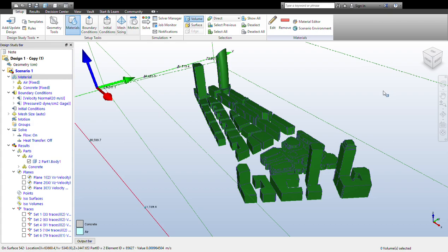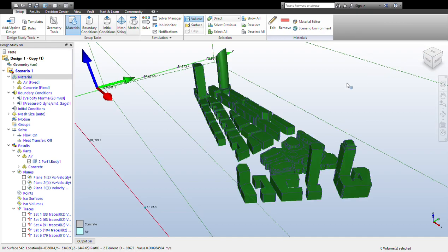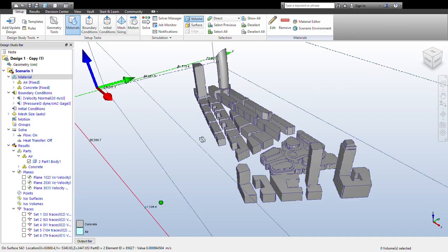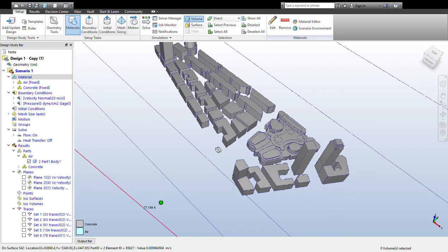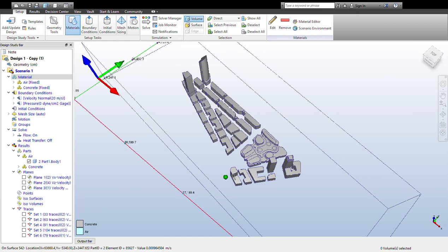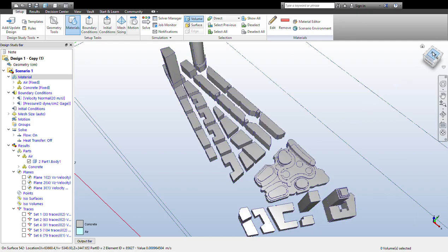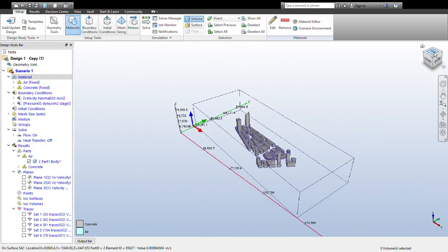What's important here in this demonstration is to show you the behavior of wind in areas such as Al-Abdali, where the shape and the location of the buildings might generate unexpected wind loads in specific areas due to generation of tunneling and might generate even uplift forces.